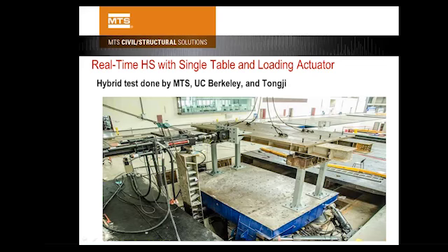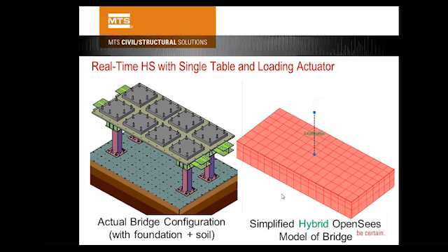About 3 years ago, we did a test at Tongji University, where MTS teamed up with UC Berkeley and did this real-time hybrid simulation simulating a bridge. The foundation is in the numerical substructure, and the inertial effect of the weight is also in the numerical substructure.